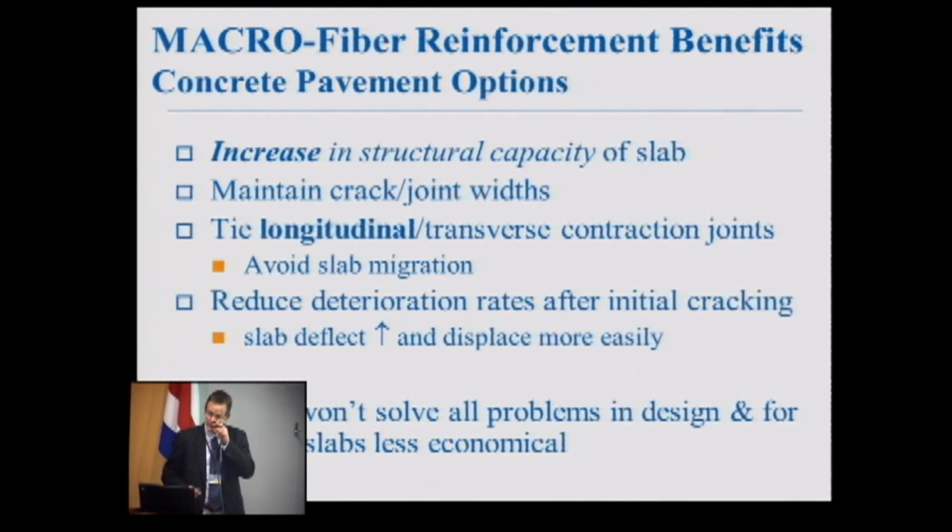In terms of fibers, I think they have a great potential for these thinner overlays, and we've seen their performance right now for about 10 years. It's working well. They increase the slab capacity. They keep cracks tightly together. They hold slabs that are short, the short panels, together so that they don't misalign. And they reduce the deterioration rate.